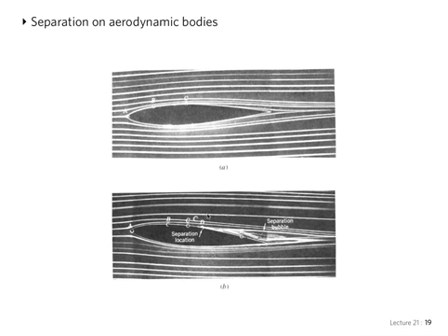Beyond a certain angle of attack, the particles of fluid are not able to go all the way to the trailing edge, and they separate somewhere around here, producing what's called a separation bubble, if you can see that. This increases the drag immediately, decreases the capacity of the airfoil to generate lift, and eventually is what we call stall. And regardless of how small the viscosity, this effect is always present.